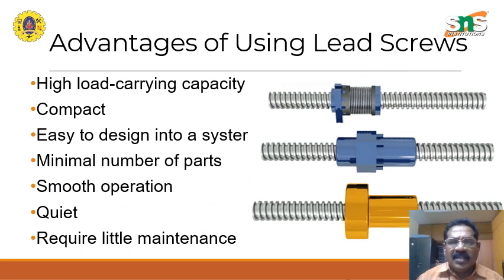The advantages of lead screws are that it carries a heavy load capacity. It is quite compact. It is easy to design into a system. A very minimum number of parts are there. Smooth operation is there. It's quite quiet also. It doesn't make any noise, and it requires very little maintenance.